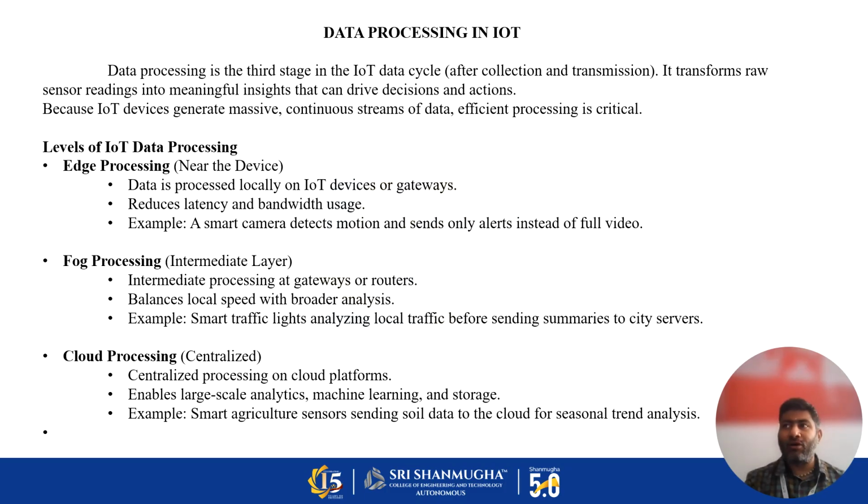The pump has been switched on, the water flows, and the moisture level goes up. Then again, the sensor sends some data. The moisture level has gone above my set value, so my processor will send a signal again and my pump will be switched off. All these things will happen in real time.